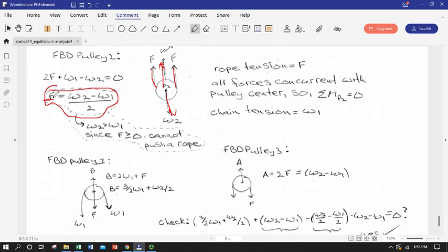It is a tension member. You can't push it. It can't go into compression. So the relationship between W1 and W2 is whatever it takes to keep this expression positive. Well, for that to be true, all you have to say is W2 always has to be greater than W1. So that's the answer to the second.